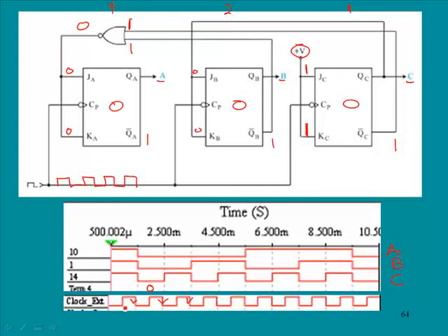So when that first clock pulse comes in right here, excuse me, this is for 0, it'll be actually right here. It will cause this flip-flop to trigger, and it'll place a 1 on the output, as I just indicated here. It places a 1 at QC's output, and we have the count of 1, and these two will remain at 0.